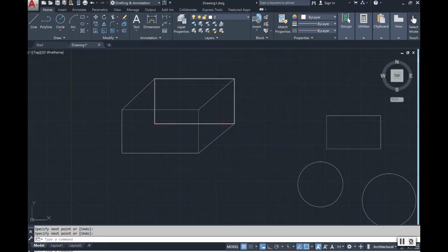But I want to hide these lines inside, right? I want to hide the line that goes down here vertically and then horizontally across so that it looks like it's just one cube. To do that, you would think that, oh, I want to go ahead and delete. But I can't delete or erase just these lines because remember, they came in as 1 unit. So what we need to do is to explode. And that explode command is to go ahead and select your object that you want to separate and make all of these lines individual.